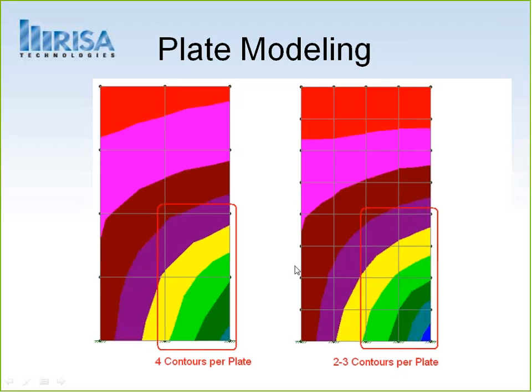If you're working in steel plates, where you might have sensitivities around openings, this is an area where I would recommend you pay close attention to these contours. If I'm working in concrete, for example, where I'm averaging over a design strip, it might not be as important to catch a very high stress riser, because it's going to be averaged over a larger area. But it's still something to make sure you identify, if you need to point it out and look at it closer. You probably don't want to go over that many color variations in one plate for your contours.